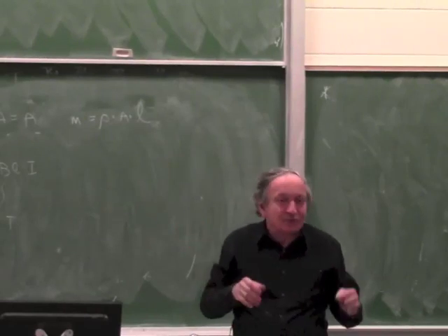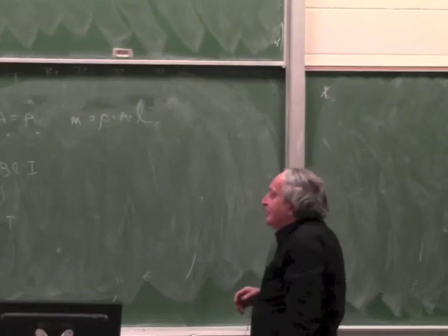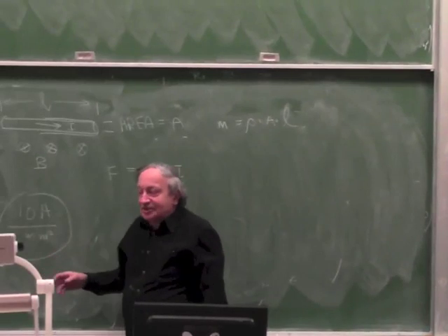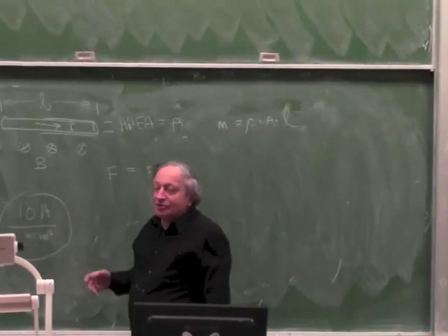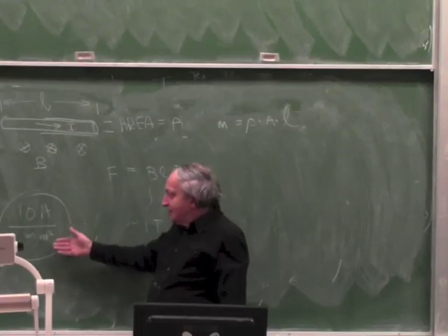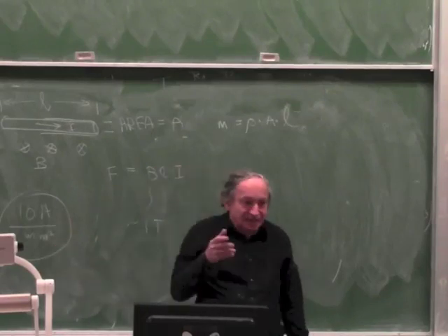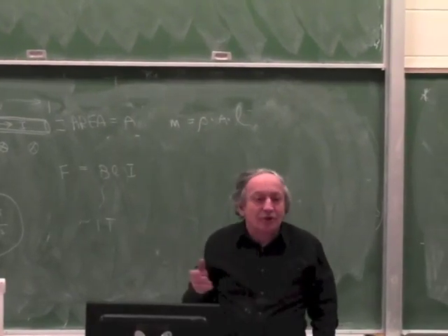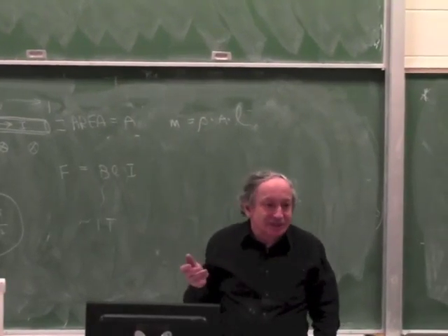So that's kind of a good rule of thumb when you make coils. You don't want to run more than 10 amps per square millimeter, because this power density corresponds to a certain delta T. And if you run it at this density, the delta temperature will be moderate. Moderate meaning the coil will heat up 30 degrees or something like that.